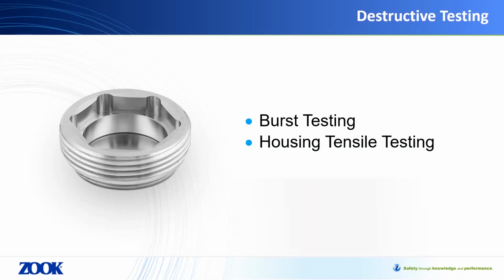After first burst testing the rupture disc contained within the housing and collecting data, the device should then be hydraulically pressurized beyond what it will see in the application to validate its ultimate strength. This is intended to ensure that theoretical calculations align with actual performance in the field. Every weld design that is applied to an inline component should undergo this stringent testing requirement.